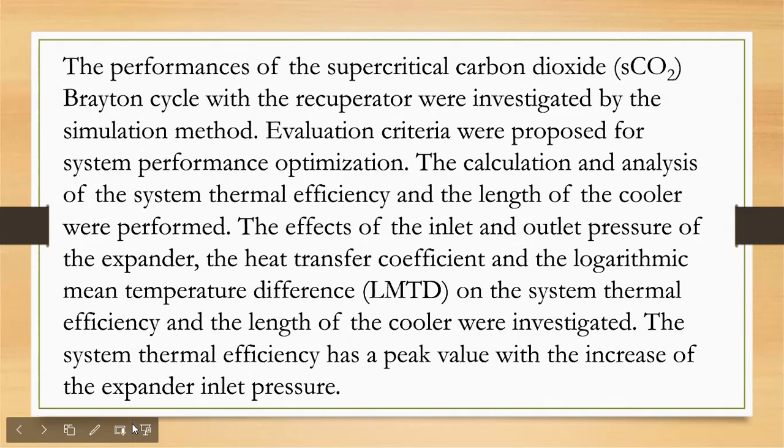The effects of inlet and outlet of the expander, where the function of the expander is to reduce the pressure, and the heat transfer coefficient and logarithmic mean temperature difference, which is called LMTD, on the system thermal efficiency and the length of the cooler were investigated. The system thermal efficiency reaches a peak value with increasing expander inlet pressure.